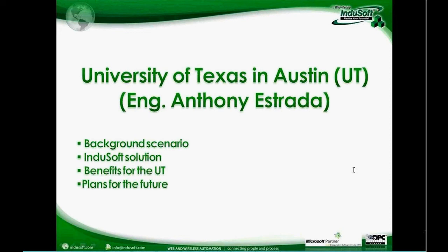There is one question here, what PLC do I recommend for building automation? That's a hard one to answer because different projects have different needs. Depending on the market, for instance, in detention, we have worked a lot with Honeywell PLCs. They are pretty much the standard for that industry. In other industries, we have worked a lot with Beckhoff PLCs as well.